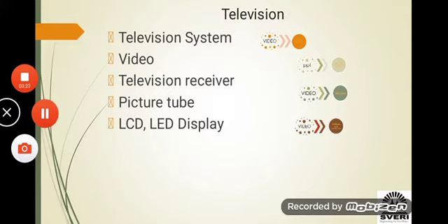Now, in the television industry, we go not only for the video part, we also go for the audio part. So amplification of the signal will take place, followed by modulation of the video signal. Parallelly, a similar thing will happen with the audio signal. Then there will be a combining circuitry, and both the signals will be combined together, amplified together, and then transmitted through air in the form of electromagnetic waves.